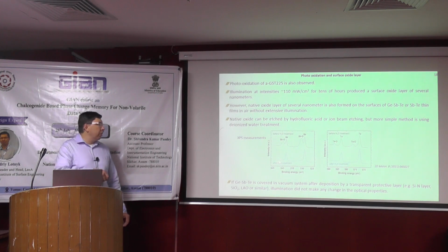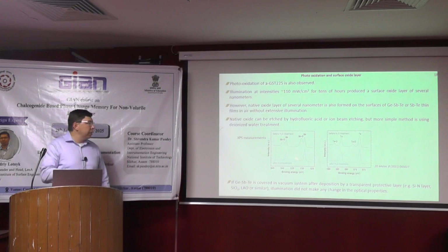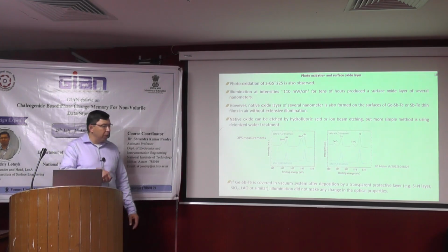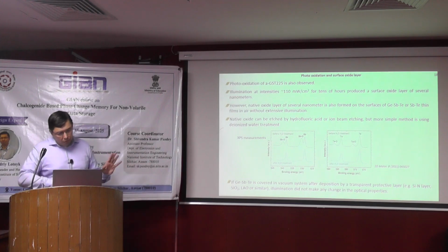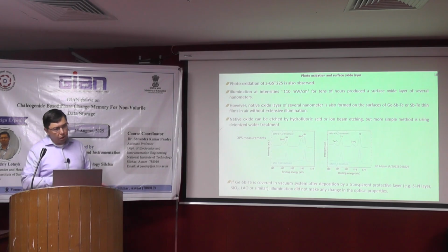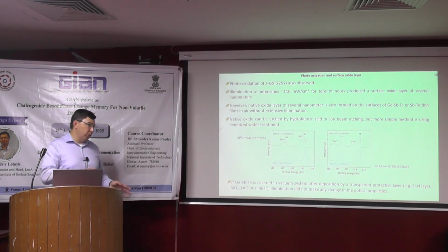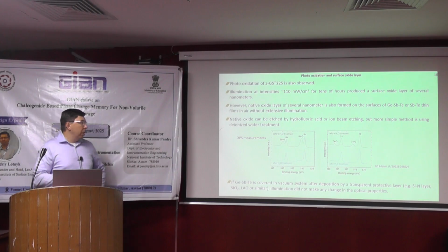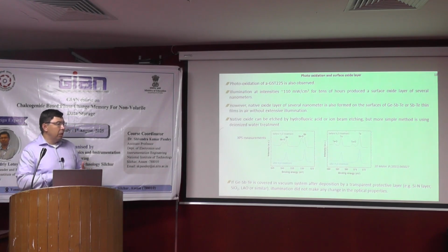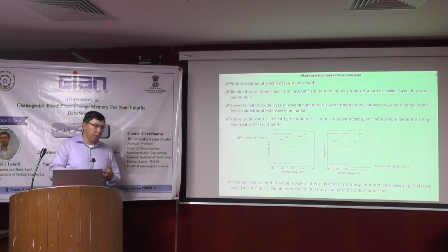So this is after water treatment, and the surface of such a treated thin film stays without oxide for several minutes. And this is more than enough to transfer from one chamber to another if you want to make contacts on your devices. Another way to overcome this oxide layer is to deposit a protective layer directly in your system.